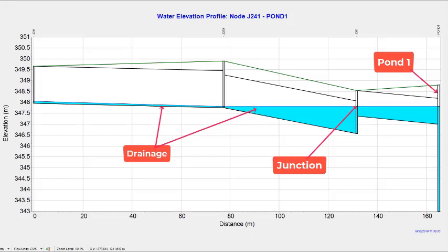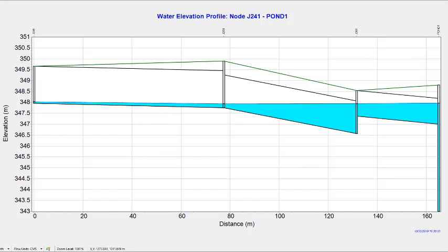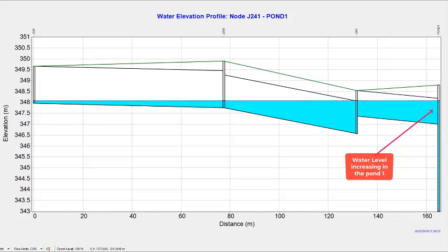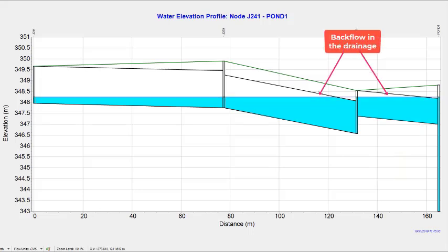Otherwise they are working normally. In this specific graph, you can see what kind of levels there are at various nodes, like in tanks and in channels, etc. when the backflow is happening in the drainage, when the flooding is expected.